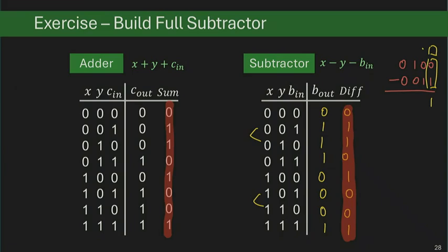that's true, right? 1 minus 0, or like 0 minus 1 minus 0, you're off with 0 by an odd number of 1s, right? Even though it's on the negative side and sometimes on the positive side, like 1 minus 0, you're always off with 0 by an odd number of 1s. So that's the reason why difference can again be implemented as an XOR gate. Adder is kind of easier to reason. That is, when 3 of them are 1, so you get either 1 or 3 at the output, right? And that is an XOR function, an odd number of 1s producing a 1.